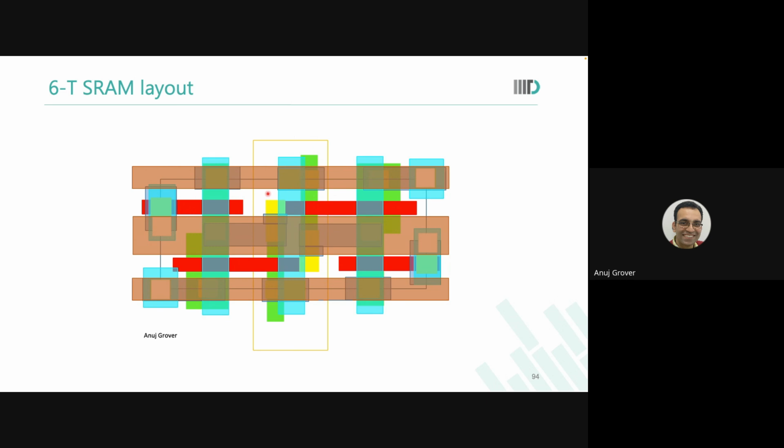First, to reduce leakage, because most of the cells are off at all times. So in the same area, if you can reduce leakage a little, good. Your devices are also very small. You're also violating so many things. The short channel effects are also very pronounced. So you want to reduce all those aspects.